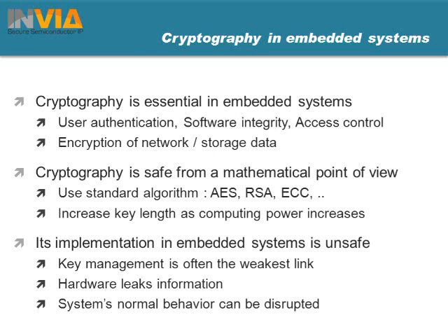So the biggest source of bad implementation of cryptography is key management. The way you move the value of the key across your system, the way you store the key into memory, even at the protocol level, the way the keys are generated or created, that is the biggest source of weak cryptographic implementation. Now, if you've done this properly, the next biggest source is that your hardware itself leaks information.